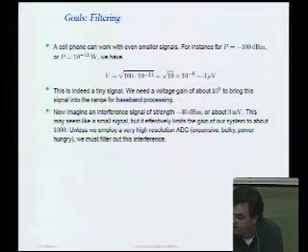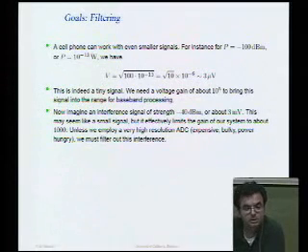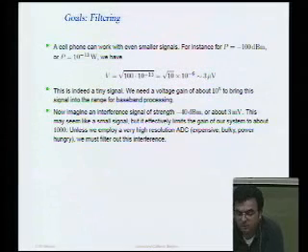But the problem is it's so much bigger, right? It's 60 dB bigger than the signal that we're trying to observe, right? And that means that if we just simply were to apply gain to our system, that interferer would actually limit the gain of the system to about 1,000.